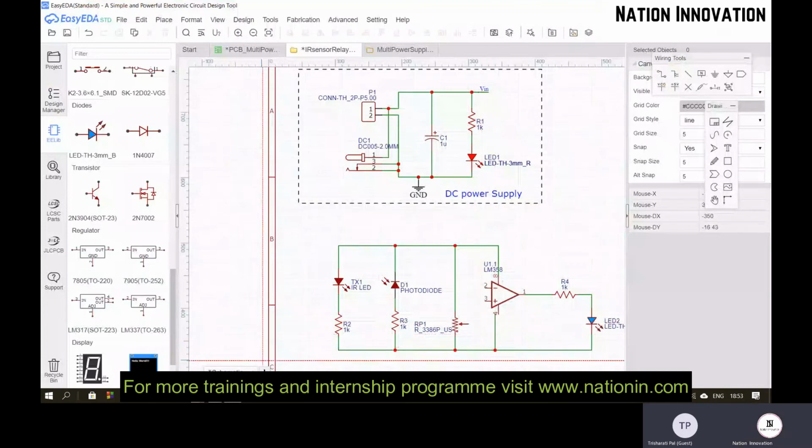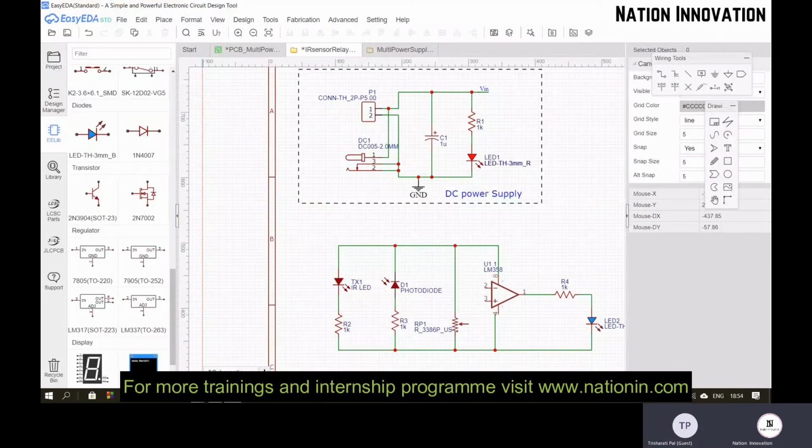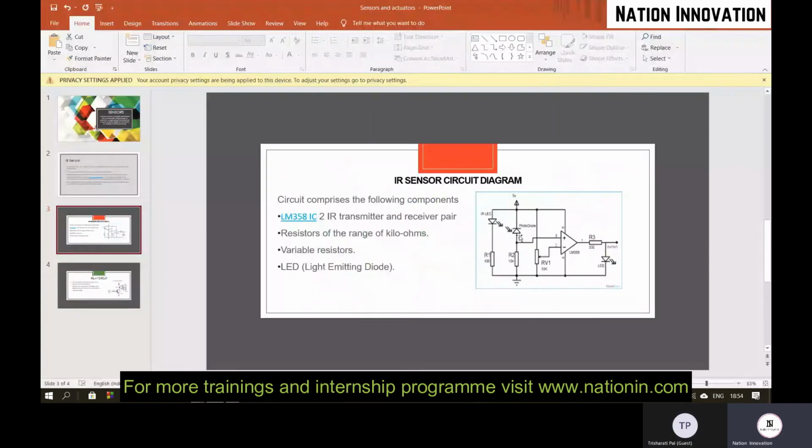And this potentiometer terminal is connected to the inverting terminal. Negative indicates the inverting terminal. So my inverting terminal is the second pin, so I have given it here. And this positive terminal is connected to the junction of this photodiode and the resistor.